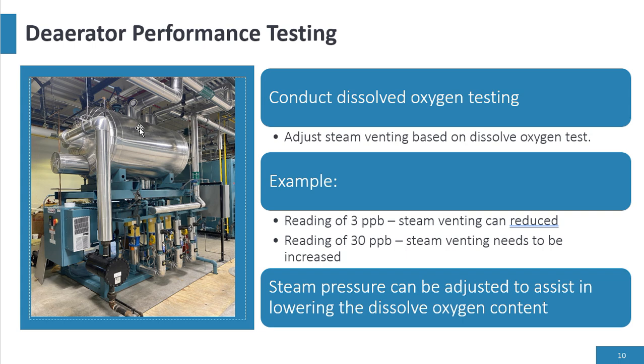We always say a deaerator should operate at 6 psi. That's just a ballpark number. It can be 9 psi, it can operate at 5 psi, 15 psi, even today a deaerator may operate at 100 psi. It's just to make sure that the deaerator is getting rid of the non-condensable gases.